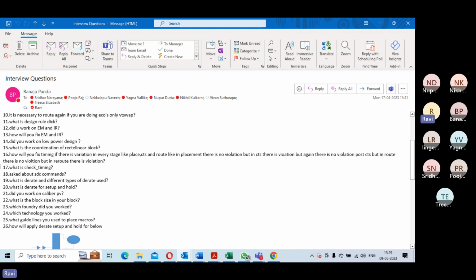Yeah, that's basically reducing the resistance. See, how will you bring down the IR drop? Either you have to reduce the current, or you have to reduce the resistance, right? Or the third one is you add decoupling, so that the voltage is charged for the dynamic case. Yes. So sir, what are the solutions to reduce the current?